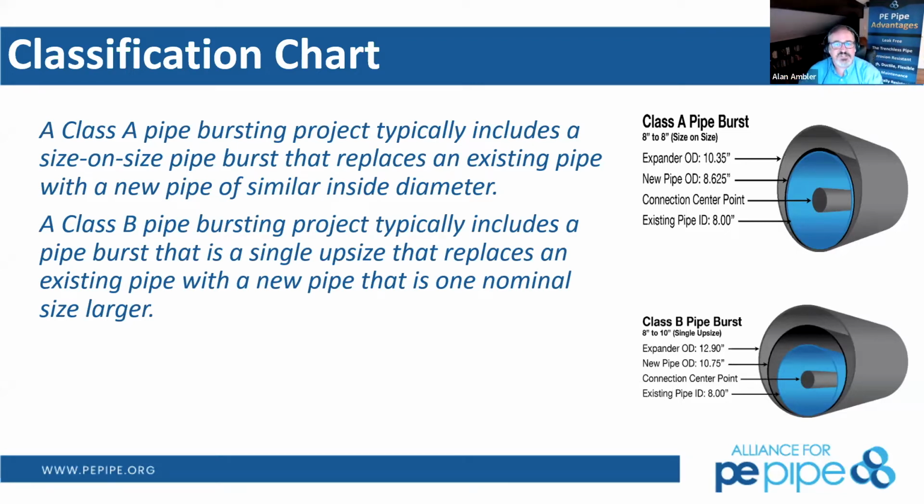So if we have sensitive laterals at low slopes and in gravity sewer, when we're raising that, the industry has created a low rider saddle, which can go below that theoretical spring line for the pipe.